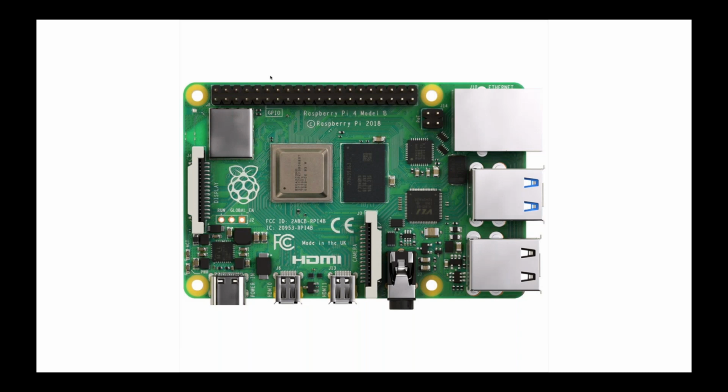So what I wanted to do was take this Raspberry Pi and connect wires from the little pins here to the ports on the Circuit Playground circuit board, and then have the ability to send electrical signals from the Raspberry Pi, mimicking me actually pressing one of the drum machine's buttons physically. So what I was able to do then is develop an Appium driver for the Raspberry Pi that lets me write an Appium test to say when these different pins on the Raspberry Pi should emit or stop emitting electrical signals.